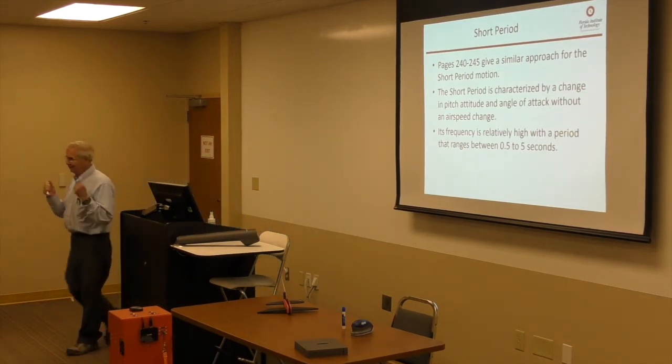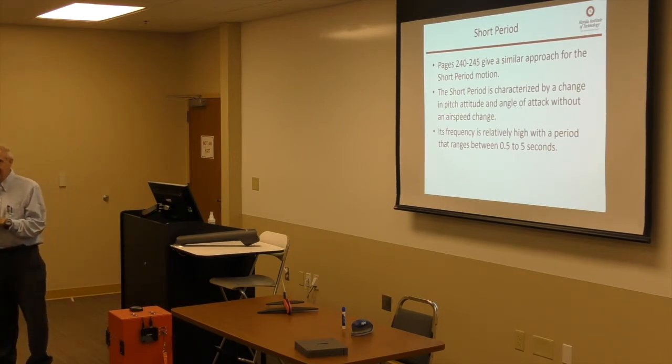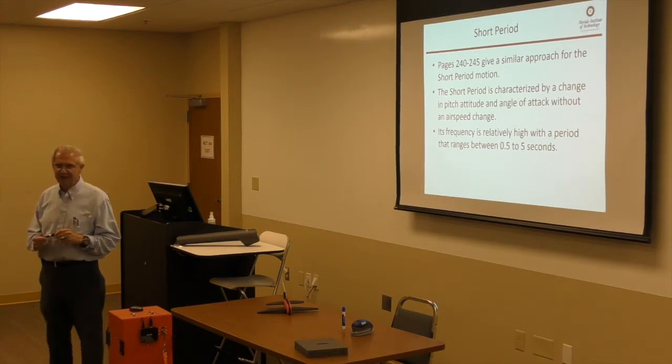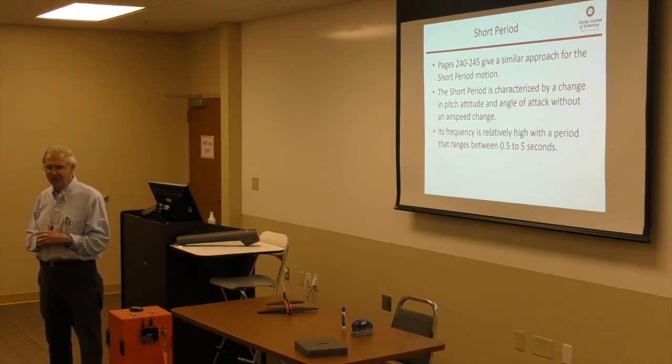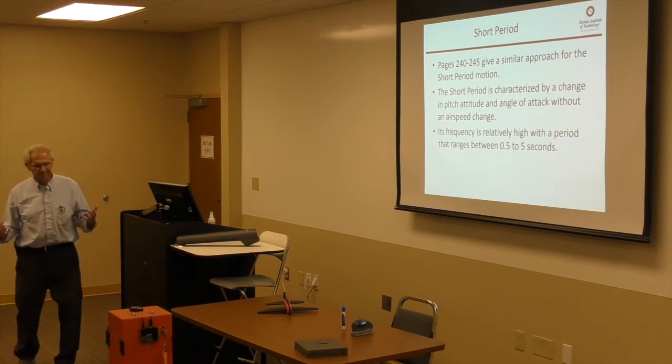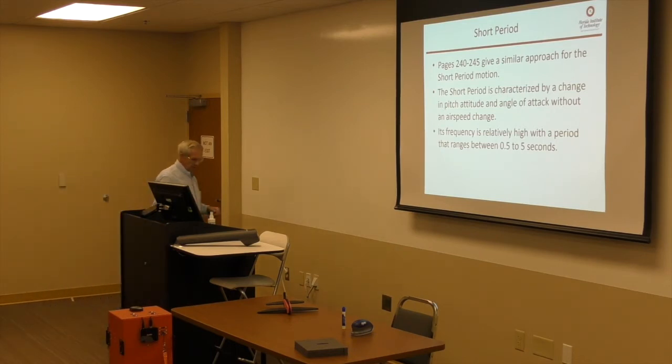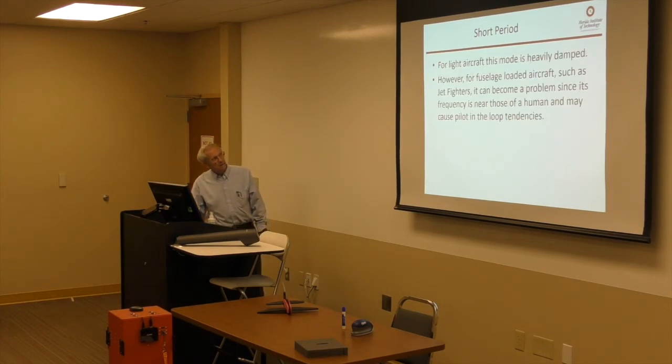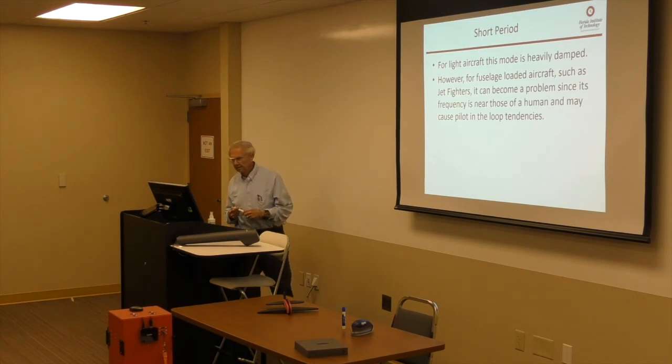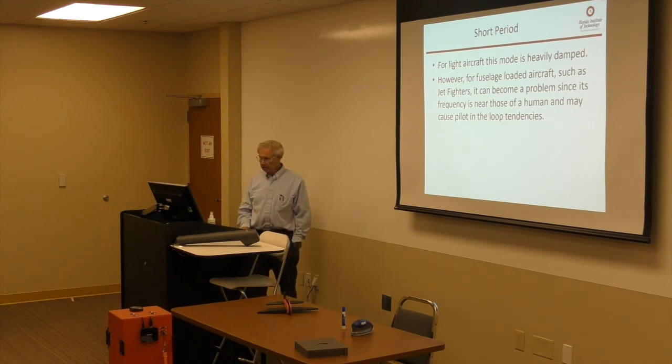As with the Saratoga, I'll do some doublets to look at the short period, but you won't see much response. We did some yesterday with the lunchbox. I don't know, we had more than about one overshoot, right? It was about what it turned out. So generally light planes are very heavily damped. Fuselage-loaded airplanes, I already mentioned that, can become a problem since frequency is near those of the human. The pilot gets in the control